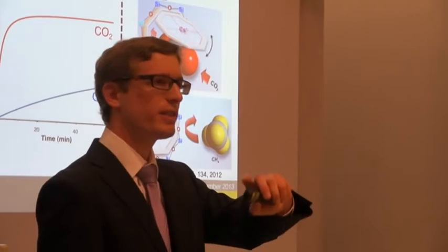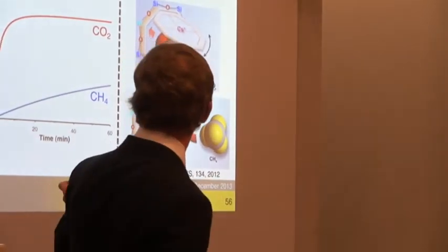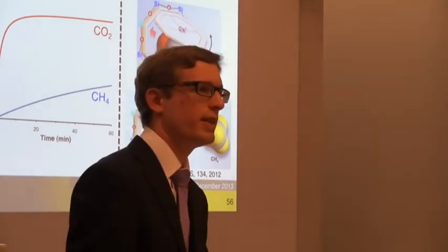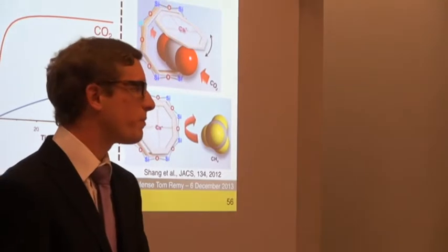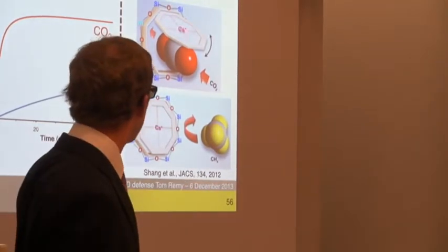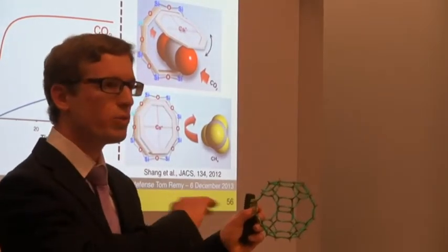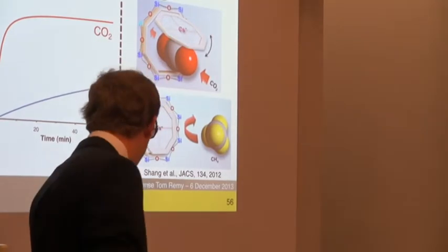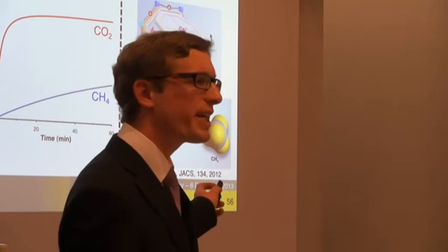The final comment I want to make is about the trapdoor effect. I already talked about the equilibrium effect and the kinetic effect. Is there also an impact of the trapdoor effect on this zeolite? Well, the trapdoor effect is that one molecule is strong enough to push away this cation and go in. CO2 can do this, for example. This has been shown by one of my colleagues in Australia, Dr. Chang. He discovered this mechanism.